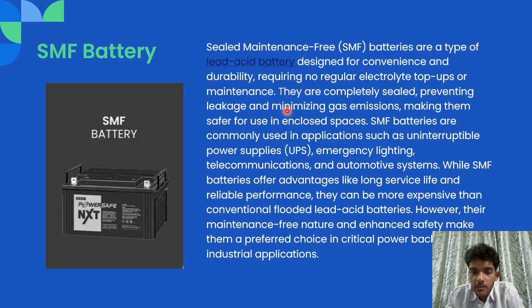These are completely sealed, preventing leakage and minimizing gas emissions, making them safer for use in enclosed spaces. SMF batteries are again commonly used in applications such as uninterruptible power supplies, UPS, emergency lighting, telecommunications, and automotive systems. While SMF batteries offer advantages like long service life and reliable performance, they tend to be more expensive than the average lead acid battery. However, their maintenance-free nature and enhanced safety make them a preferred choice in critical power-backup industrial applications.